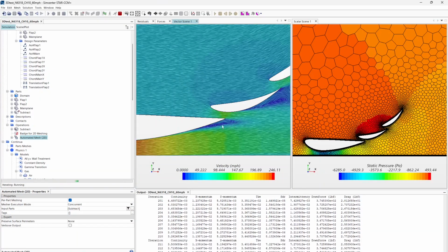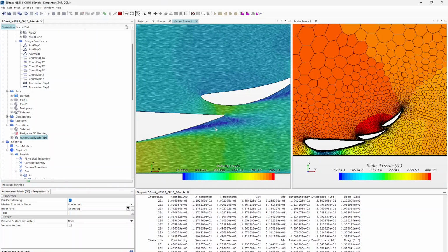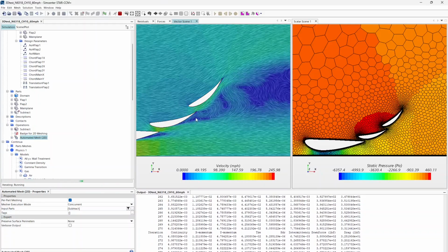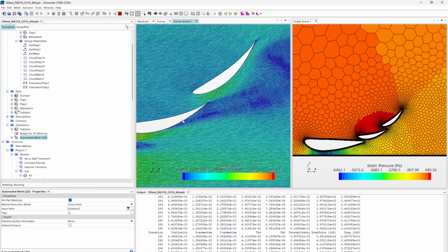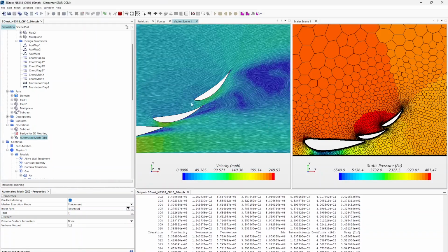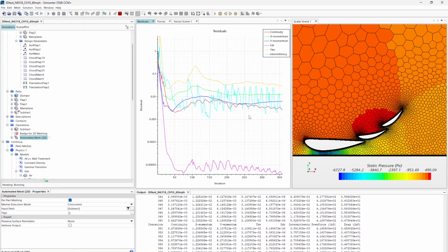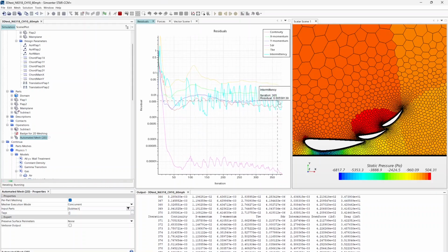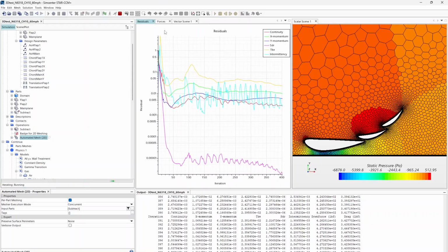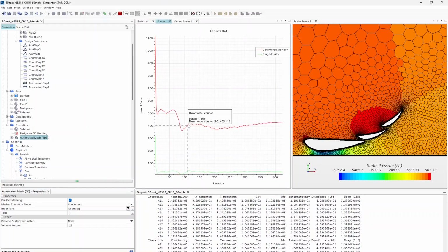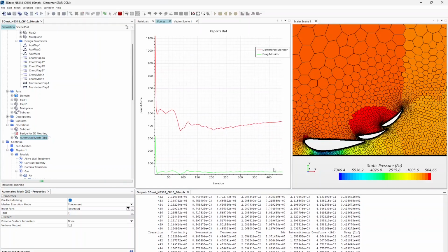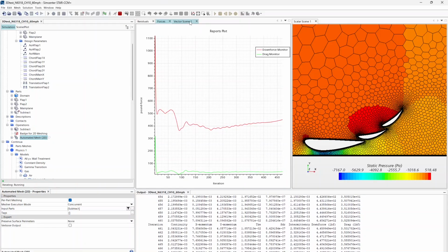So we've kind of solved the issue, not much, but we might have slightly improved the trailing edge here. However, we have greatly worsened the effect of this trailing edge here. So we would need to go in and change this, because we'll see on our residuals plots that now our separation is even worse. So our intermittency is going up and down even worse than before. And our forces aren't going to level out steadily either because of this popping up and down.